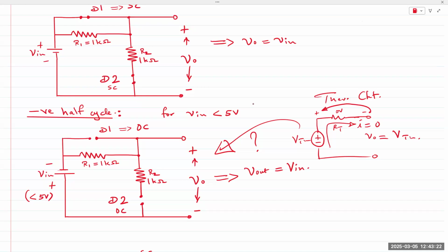Take a DC power supply, clamp a resistor to it. You don't even need a breadboard. And just measure the voltage between the negative end of the power supply and the open end of the resistor. If you apply 5 volts, you should get 5 volts. Okay. So again, when the circuit is open, if you have a resistor with an open terminal and you measure the voltage, it'd be exactly the same as the other end of that resistor.